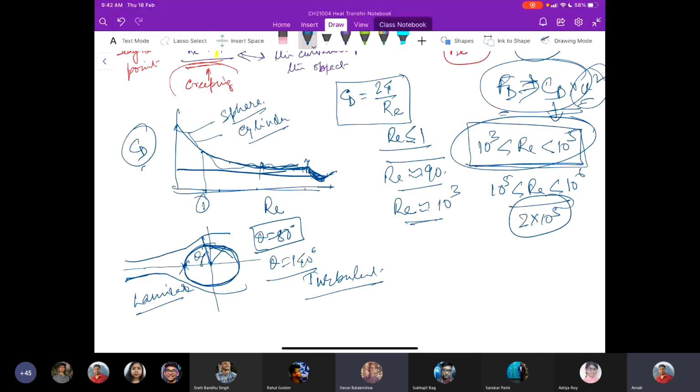And there, those roughnesses were in the turbulent flow region, because surface roughness increases the drag coefficient in the turbulent region. And this typically happens with streamlined bodies, that means when the object is aligned with the flow streamline.